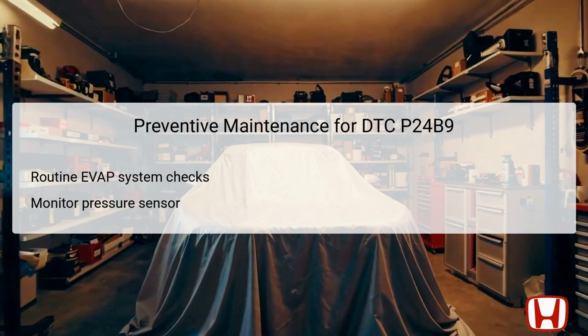Routine checks are essential to identify any potential blockages, ensuring that components like the canister one-way valve and drain tube are free from obstructions. Additionally, monitoring the pressure sensor for any irregularities in performance can help catch issues early before they escalate into more significant problems. Regular maintenance becomes an important practice to ensure the longevity and effectiveness of the entire emissions control system. By taking these proactive measures, drivers can minimize the likelihood of triggering DTC P24B9 and maintain optimal vehicle emissions performance.